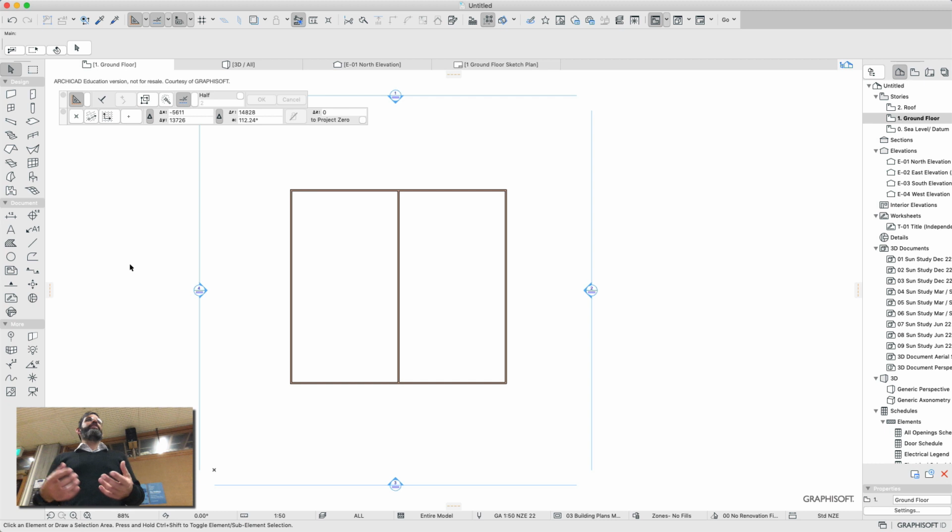That's the sort of tool you'll be looking for if you suddenly realize that all of your walls are on the outside when you should have been on the inside. Oh, crap. You also have to be careful because, of course, you draw a line in one direction. If you draw it in the other direction, it can end up on the wrong side. Okay. We all happy with drawing walls?